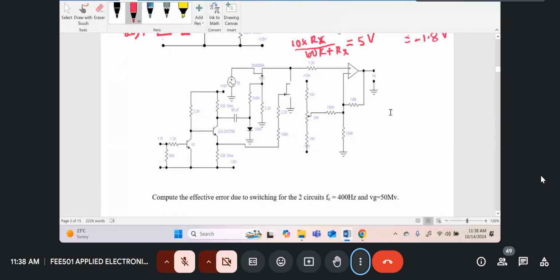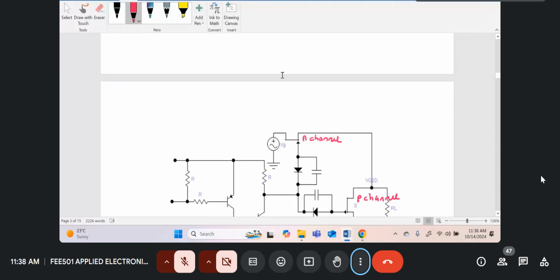And I told you also that in the lab, to use these choppers, all you need to do is to connect an oscilloscope to the output of the chopper and then raise the value of the chopping voltage or the control voltage so that the device is just able to switch on and off. Otherwise, if you use a large control voltage, then switching spikes might appear at the output, which we don't want. So there's a simple example over here which you can do.